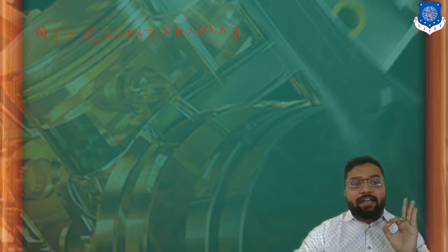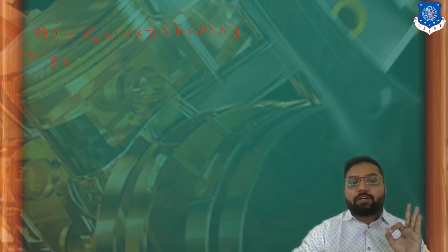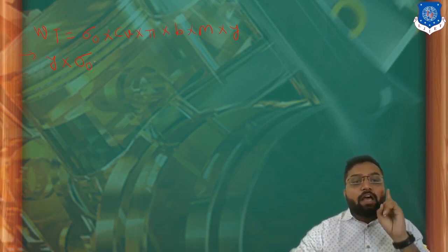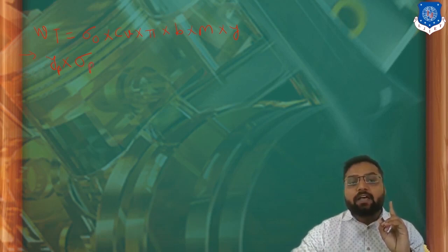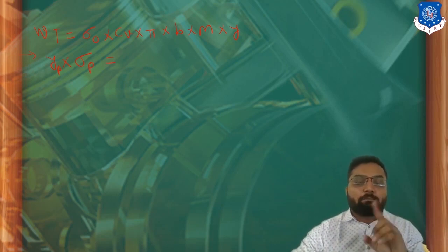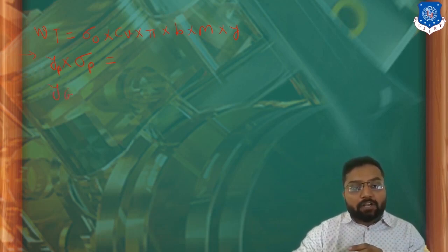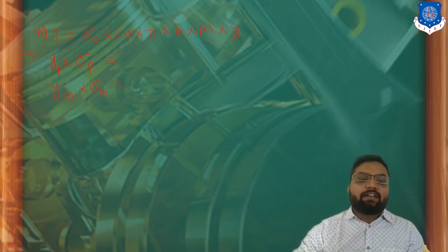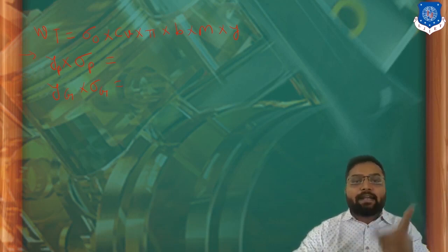Either deformation of the pinion or deformation of the gear is going to take place depending on its strength. And to find out which is going to fail first, we have to satisfy this criterion, in which the multiplication of the tooth form factor and the allowable stress, sigma p for pinion and sigma g for gear, will indicate it. We compare the product of yp and sigma p with the product of yg and sigma g, and whichever value is lesser, we design for that pinion or gear.